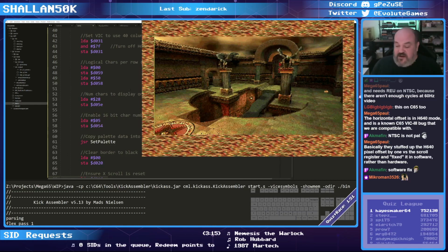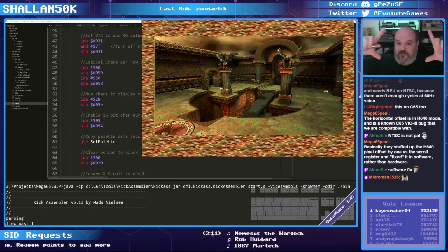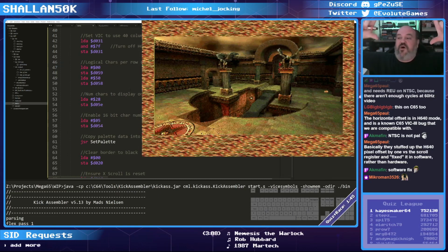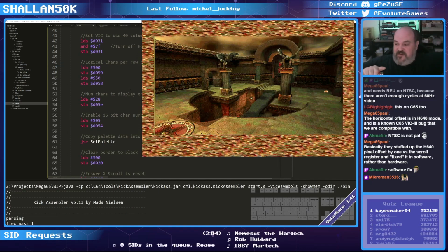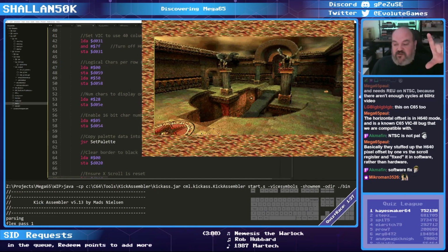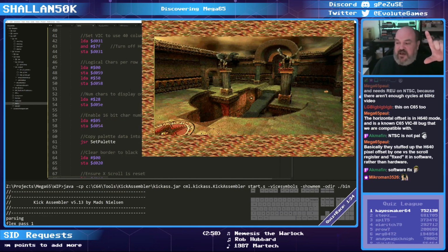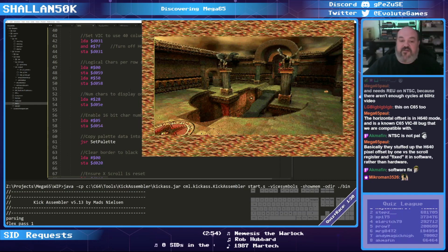Say you want to shift the screen up. Normally you would grab every one of those 1000 bytes and move them backwards in memory, 40 spaces. On the Mega 65, all you need to do is say the screen is no longer at the location you're looking at now. It's 40 characters ahead of that. And the whole screen will move up by 40 characters.